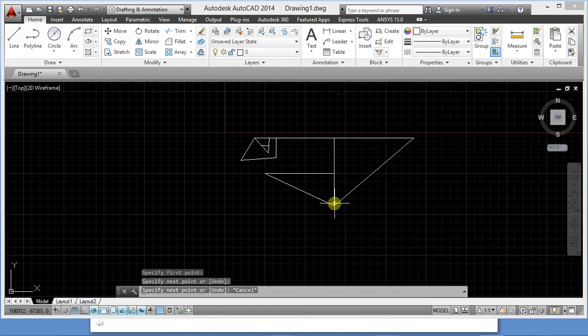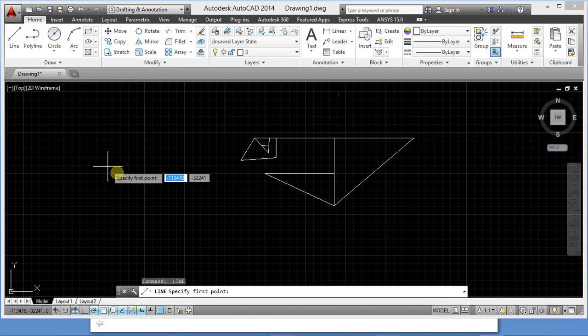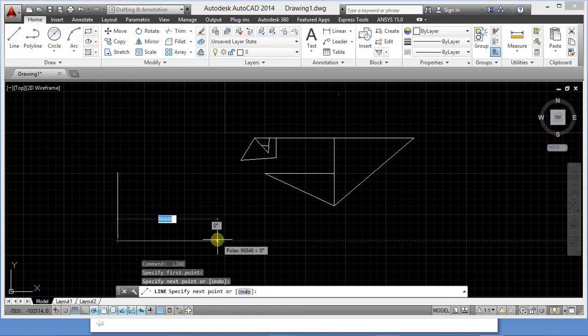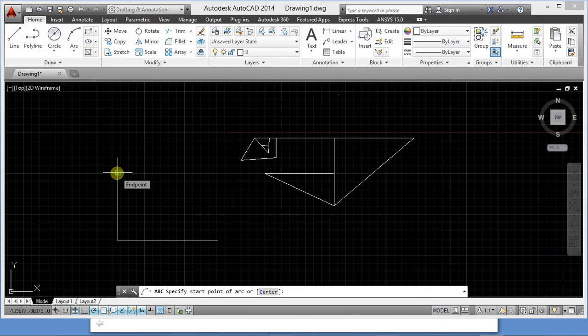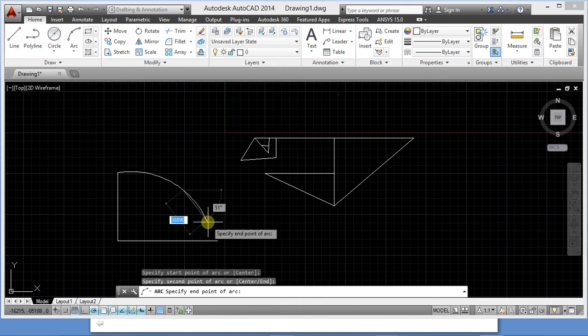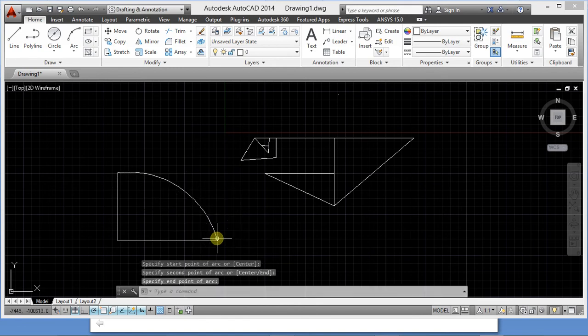As we want to sketch different parts, I want to sketch here, and now go off from that line. I want to pick an arc. I want to join this arc with this line. I think I want to make a particular sketch with a combination of different tools. So Osnap will help you to sketch with a closed loop. Did you understand? Okay, thank you.